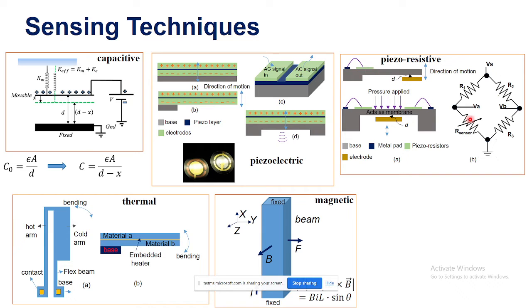And once we have that, we have a simple electronic configuration. We already know that this is a Wheatstone bridge. What we can do is that one arm of this bridge is our sensor. So this sensor has been placed in this arm. When the bridge is balanced, here is a DC voltage, let's say. When the bridge is completely balanced, the voltage difference between these 2 points is 0 in ideal conditions, assuming there is no temperature effect, no pressure effect, no surrounding effect such as vibration.